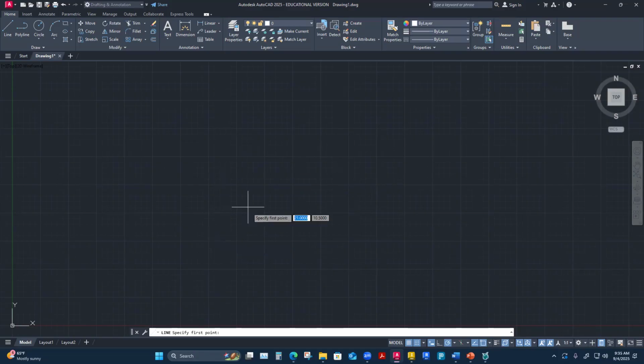It just gets a little bit joggy the way I maneuver through model space, because it's going to confine me to the grid. What I actually had on was a polar snap, which means I'm going to be able to snap to features like shapes and stuff that I've drawn. I'll be able to snap to those. So I do keep it on in the sense that I'm not totally toggling it off, which I could. I have it toggled on, but on a polar snap instead of a grid snap.